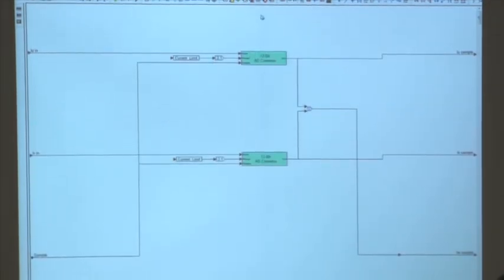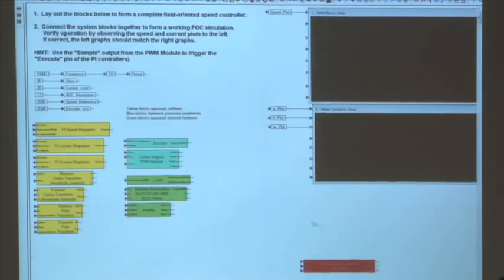I've got 2 simultaneously sampled 12-bit A to D converters. Then I take those samples, add them together and take the negative, and that generates my third current sample, as shown right here. Now I've got my 3 current samples. What's the next thing I want to do? Do you remember? Not yet. We're not up on the rotating reference frame yet.